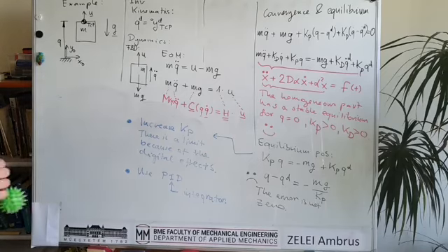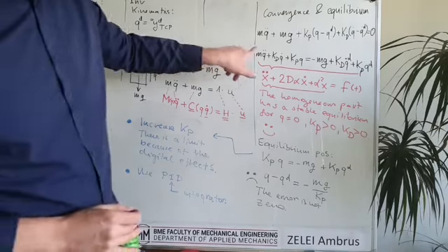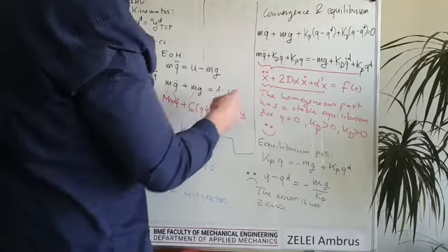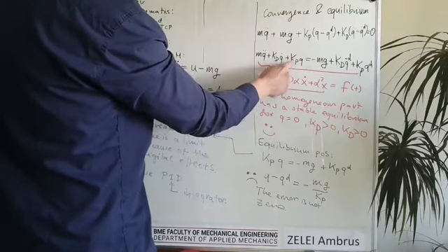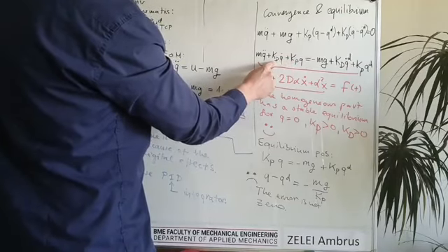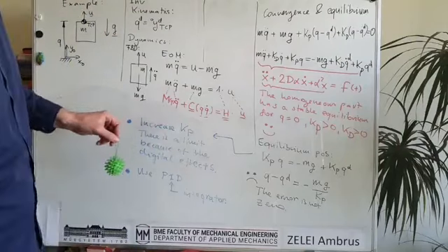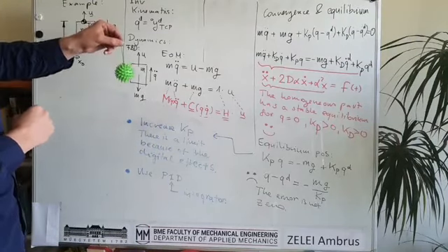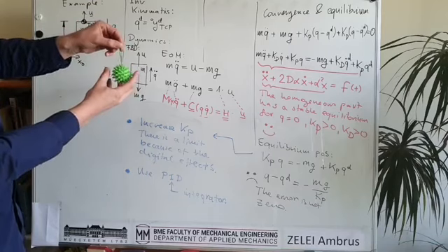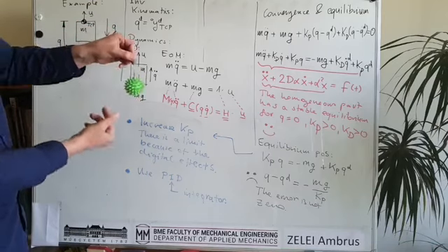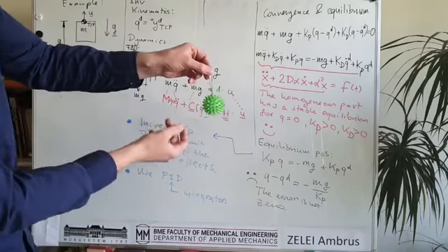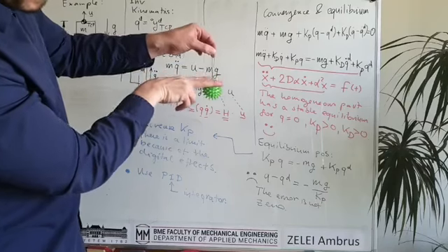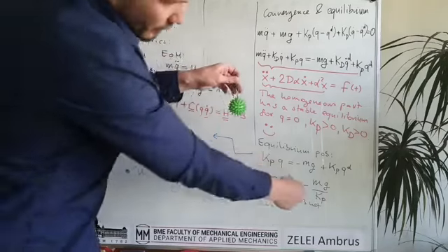What we see here is that the PD controller is very similar to a spring and damper system. It looks like a spring and this looks like a damper. So a purely PD controller will behave like a spring and a damper, like a rope made of rubber. If the gravitational force is higher, then this error will be larger.